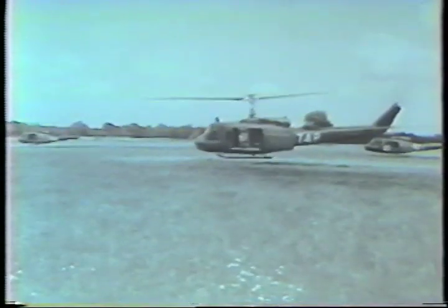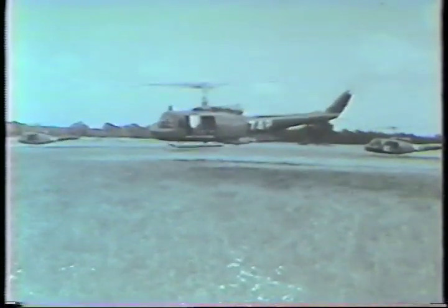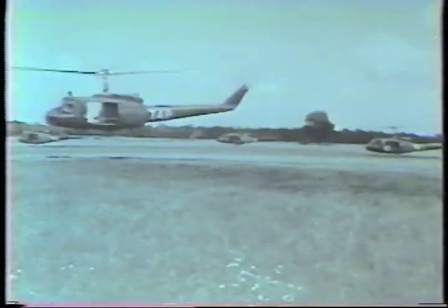During the formation flight, if an element loses all communication capabilities, it will remain with the formation to its next landing site. At the landing site, the crew members will give the visual signal, thumbs down. Since the formation leader will not be able to see the signal, it should be part of the pre-mission briefing to designate an air crewman responsible for notifying the leader. This crewman is normally in the last aircraft of the formation. After making sure the lead aircraft has been informed of the lost communications, the aircraft will break formation and return to base.